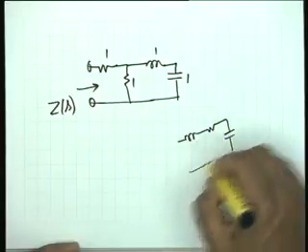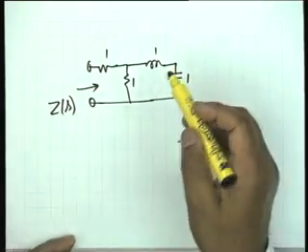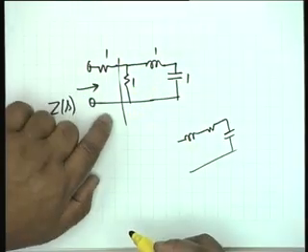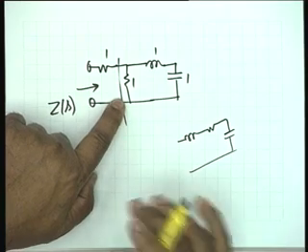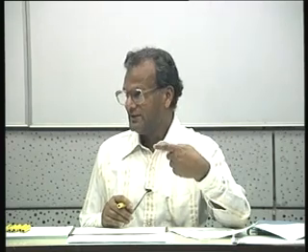No sir, the second part, 1 plus s square. Oh, the second part is okay. Second part is a parallel tuned circuit, isn't it? There is a resistance, then in parallel with it, it's not one of those circuits that we have dealt with earlier. You see, what we did was, we had a series tuned circuit in which R came in series with L. We had a parallel tuned circuit in which a capacitor came in parallel with a resistance and an inductor. It's none of them.